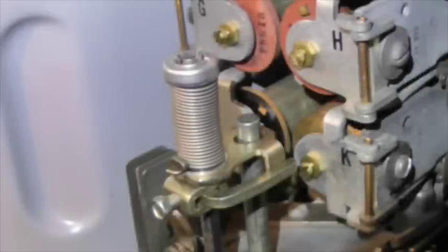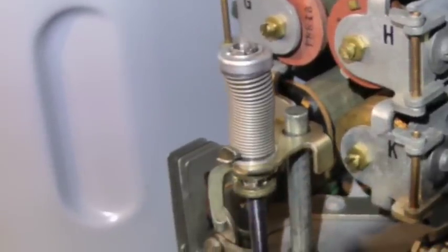Let's see how the shaft spring creates the tension required to rotate the shaft anti-clockwise to its rotary normal position when the connector releases at the end of the call. The top of the shaft spring is attached to the cap, which is fixed to the shaft. When the shaft rotates, the cap and the top of the spring rotate with it. The bottom of the spring is attached to the shaft spring bracket, which cannot rotate as it is fitted over the stationary normal post. The bottom of the spring cannot rotate, while the top of the spring can. So when the shaft rotates, the spring winds up, creating tension.